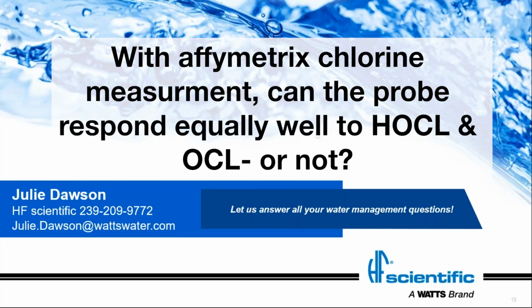It doesn't know where it is on that curve. And that's why I have concerns about using it in the higher pH waters, because in the higher pH waters, we're reading very low levels of chlorine. So any error in that probe is going to make a much bigger error in your actual answer. And the closer to neutral, where it's 88% hypochlorous acid, that's probably an okay application for amperometric technology.